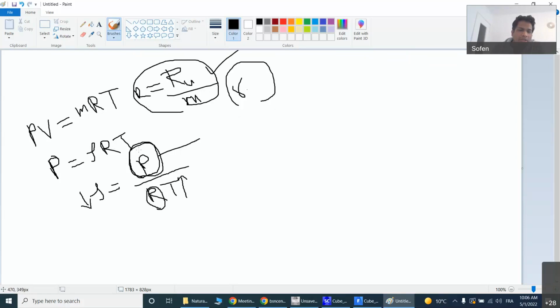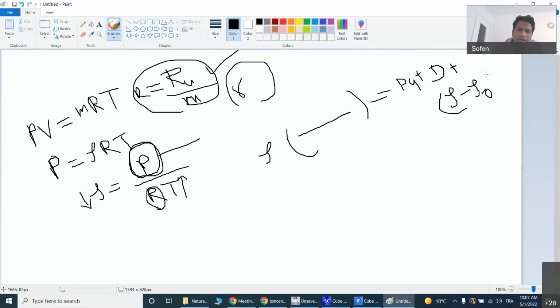Okay. So this density in the Navier-Stokes equation, where is that determined? Here you will get a convective derivative, the substantive derivative, then a pressure gradient term, then a momentum diffusion term, plus rho minus rho 0 into g, right?